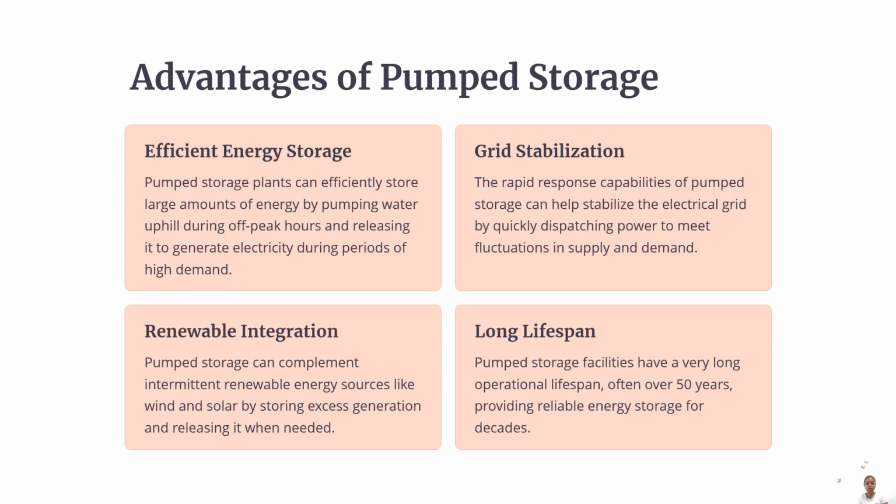Advantages of pumped storage: efficient energy storage, grid stabilization, renewable integration, long lifespan. So efficient energy storage means pumped storage plants can efficiently store large amounts of energy by pumping water uphill during off-peak hours and releasing it to generate electricity during periods of high demand. Grid stabilization. The rapid response capabilities of pumped storage can help stabilize the electrical grid by quickly dispatching power to meet fluctuations in supply and demand.